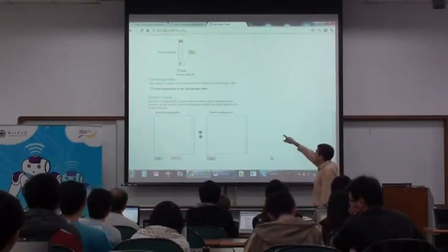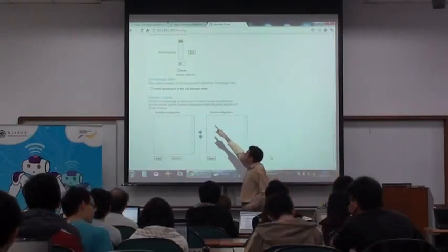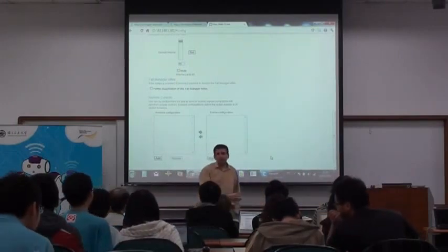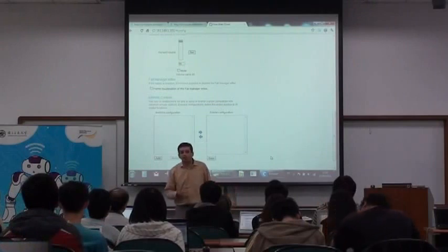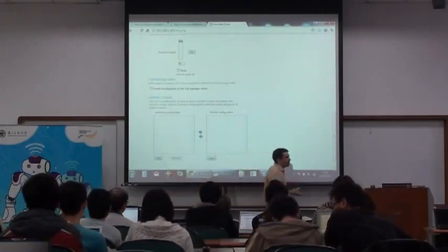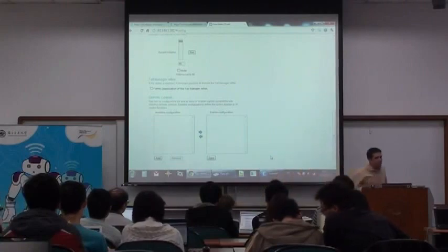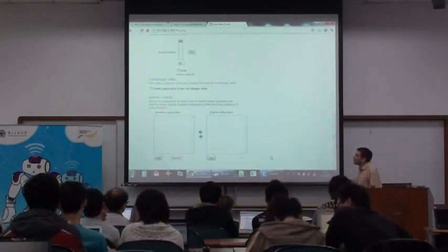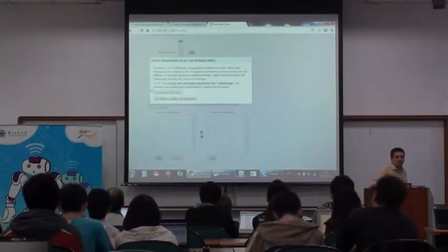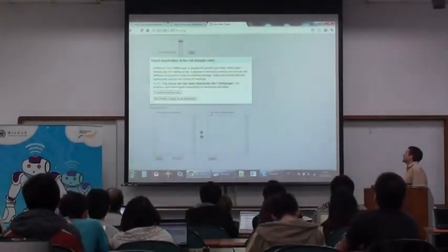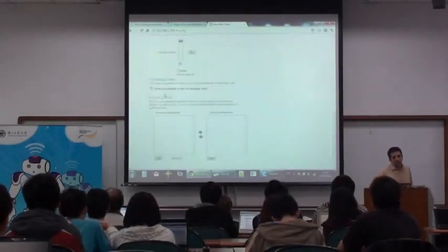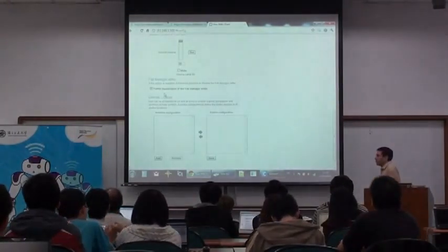But if you check this option, then you can disable the fall manager programmatically. So if you don't want to have your robot in a dangerous situation, you can just leave it like that. If you check it, you get a warning that explains you are taking a risk with your robot, and you say, okay, I understand the risk, I really want to deactivate the fall manager.